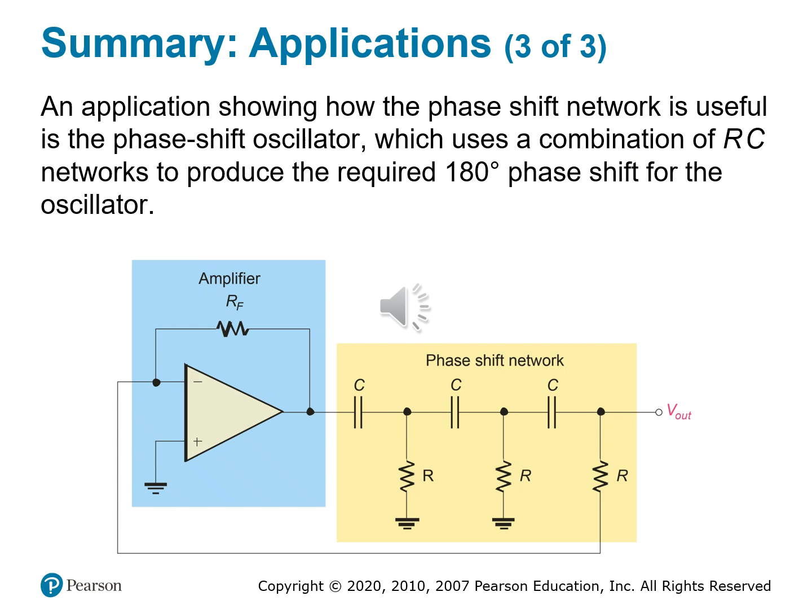So it matters because this circuit is not only a staple in analog design. The RC phase shift oscillator is simple, it's compact, it's tunable just by adjusting the resistance or the capacitance. You use it for waveform generators, in test equipment, and in audio synthesis if you're a musician, or if you're going to be an audio engineer. And here's the thing, it doesn't even need an inductor. So for designs where size, cost, or magnetic interference are of any concern, this circuit is gold. Not only gold, it's platinum, right?